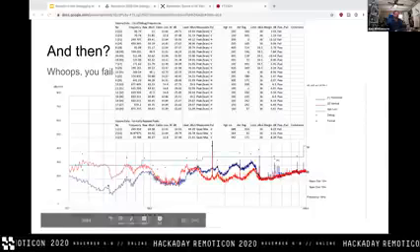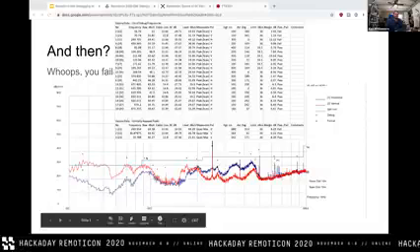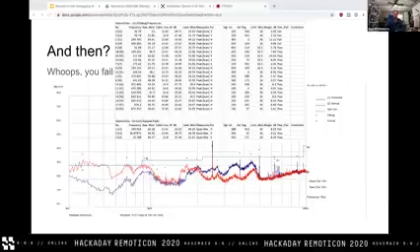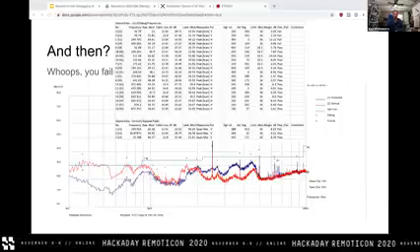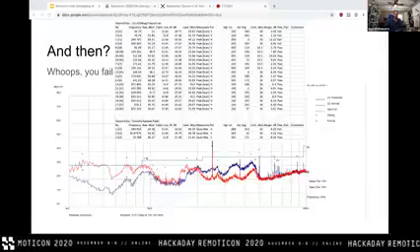This first phase of the test, where it lists debug frequencies, is sweeping the spectrum analyzer across the entire spectrum and looking for only the peaks at each point. So looking for the absolute maximum value of RF power that we see for every point in that spectrum.